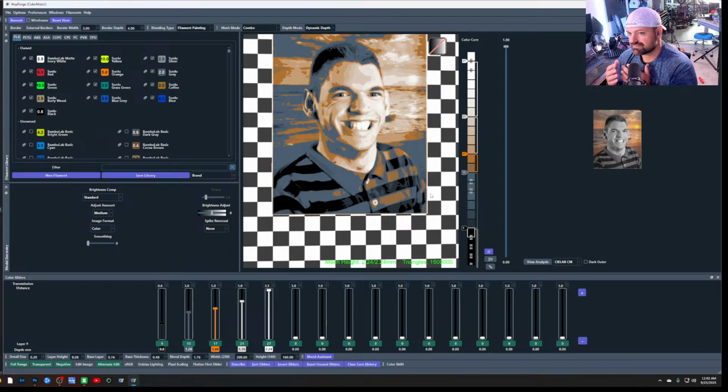Because it hasn't really started printing. So the battery backup would just be needed during the actual print, and it's not drawing as much power at that point. It's drawing all that power when it first starts up because everything's heating up and getting ready. So I wouldn't worry too much about the 1300 watts in the beginning.